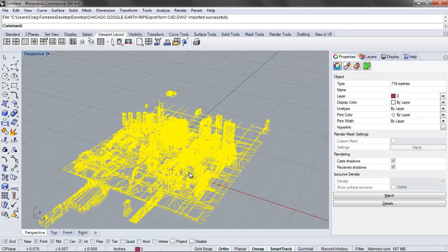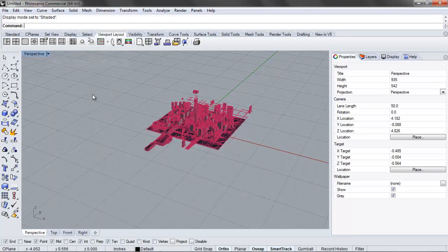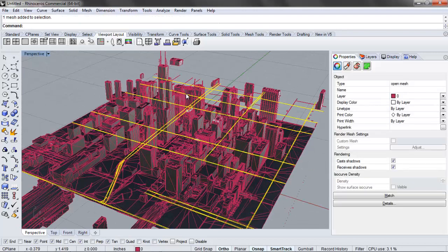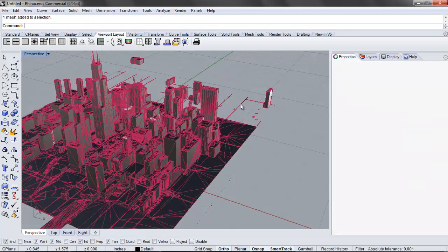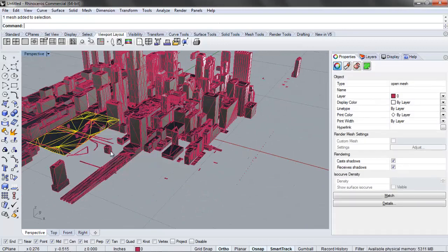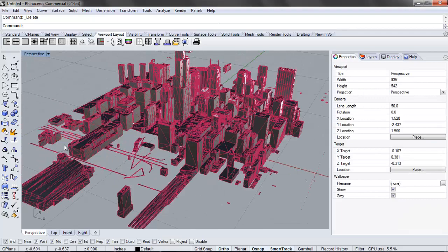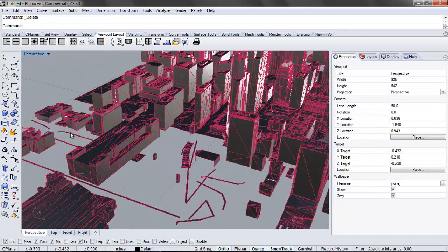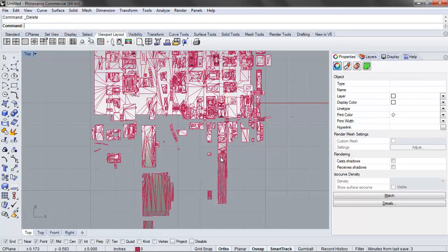Now there are a few things that we do not necessarily need for this operation. If I go to the shaded view, I don't need the streets. I see that when I did my Google Earth trip I had streets on, so I can delete those. My topography, unless you're cutting topography, we don't need it, so I can delete those mesh planes. Again, any roadways or railways I'll delete. It's probably easier to do this from the top view. I'll delete all this off.